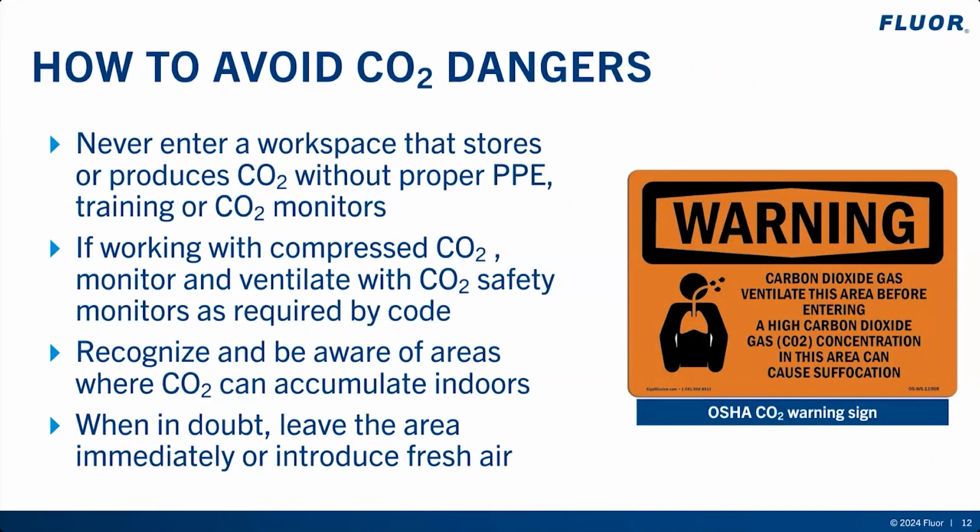How can we avoid CO2 dangers? You want to make sure to never enter a workplace that stores or produces carbon dioxide without proper protective equipment, training, or CO2 monitors. If working with compressed CO2, monitor and ventilate with CO2 safety monitors as required by code.